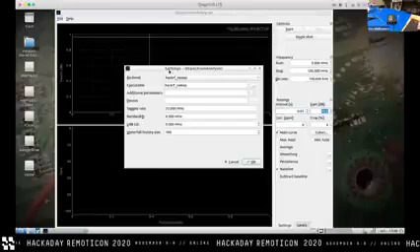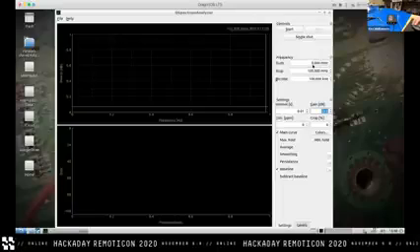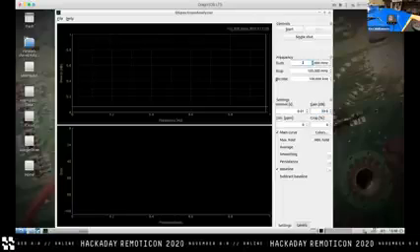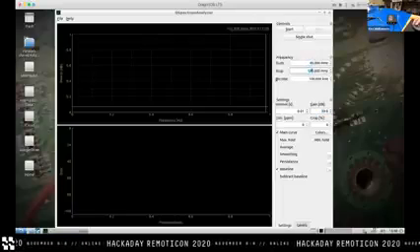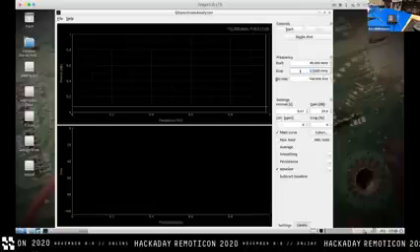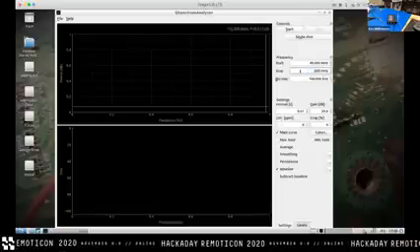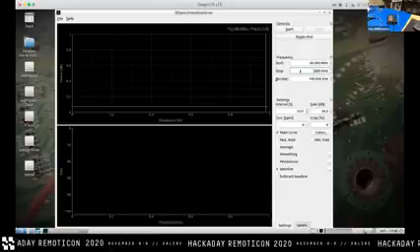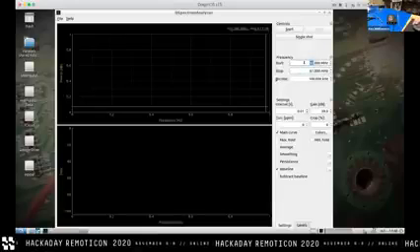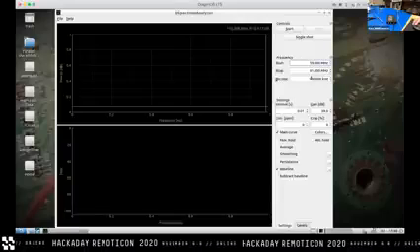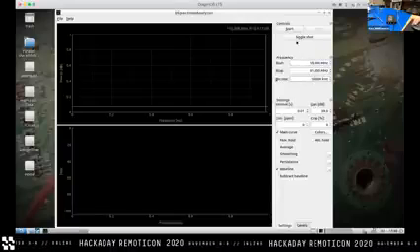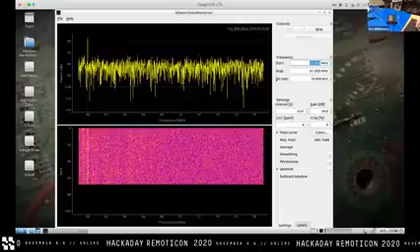We are still on HackRF Sweep. Let's go 49, 51. Oh, actually, on the board I'm going to demo, the 60 megahertz is the key. So we're going to go with 61 and 59, and bin size 10 kilohertz. Start. There we go. Cool.